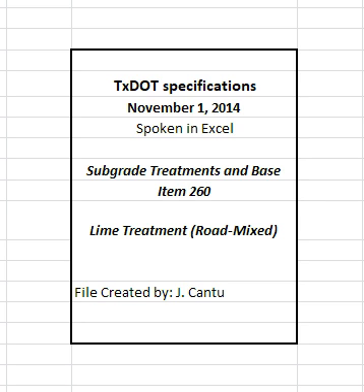4.3.1 Dry placement. Before applying lime, bring the prepared roadway to approximately 2 percentage points above optimum moisture content. When necessary, sprinkle in accordance with item 204, sprinkling. Distribute the required quantity of hydrated lime or pebble-grade quicklime with approved equipment. Only hydrated lime may be distributed by bag. Do not use a motor grader to spread hydrated lime.